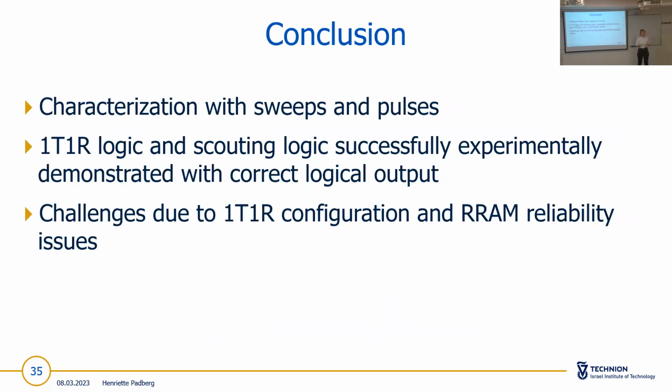So as a conclusion, in this work, I characterized the silicon oxide-based VCM cells in a 1T1R arrangement, first with sweeps and then with pulses, and found out that the cells are suiting for specific non-stateful logic techniques. And then I demonstrated two logic techniques, first the 1T1R logic, and second the scouting logic, and they all showed correct logical output. However, it can be potentially endangered if the RRAM reliability issues get more severe.